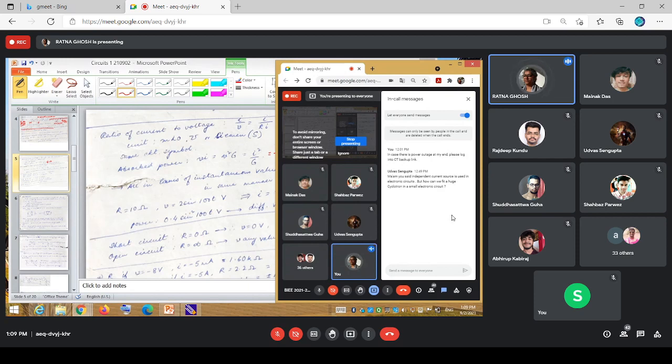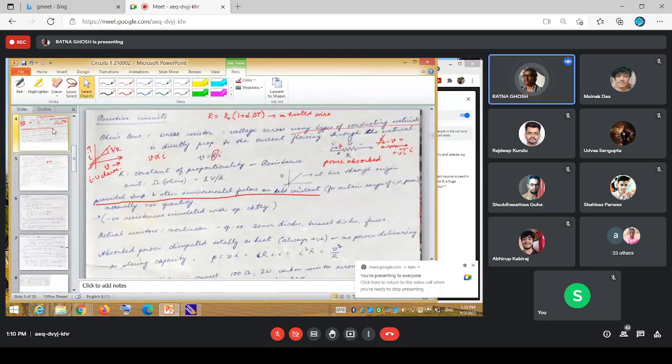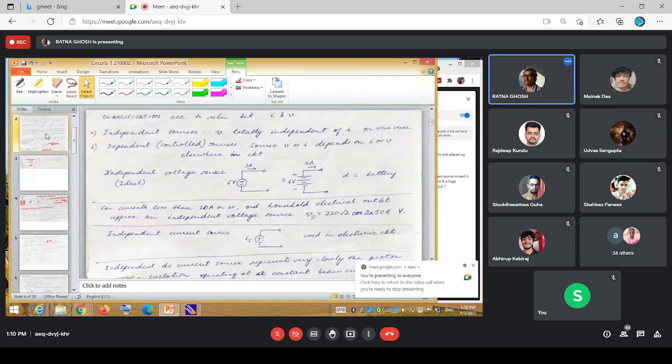But in an electronic circuit, I corrected myself later. That is that I drew that representation mistakenly. It is actually a dependent current source on the secondary side or on the output side of the transistor. Okay. Just to clarify, let me go back once, a slide or two.